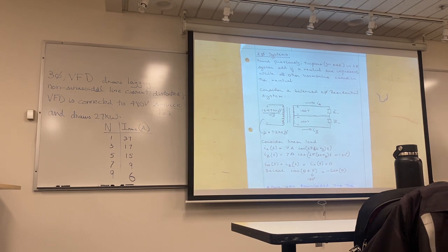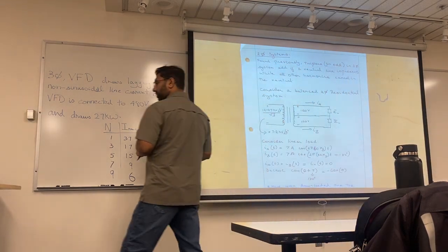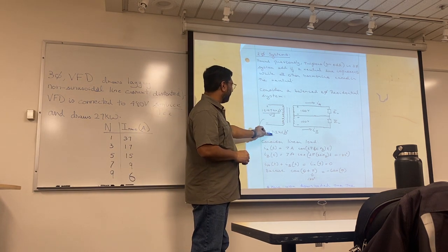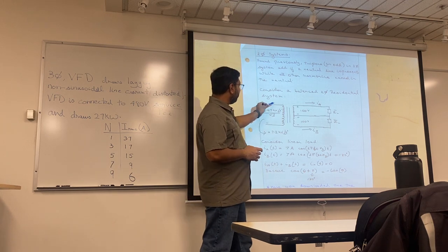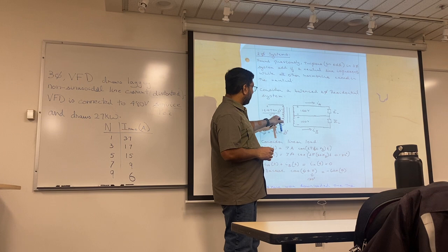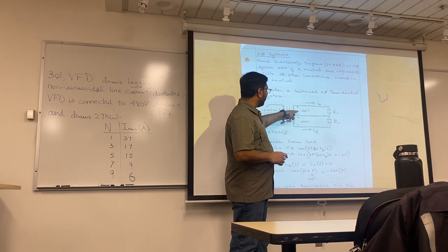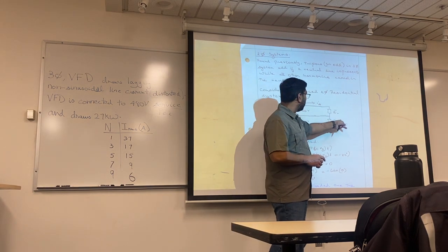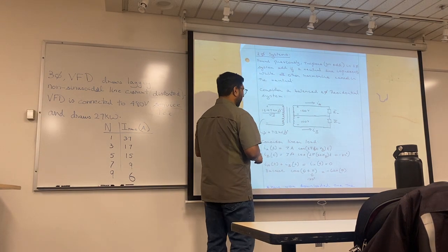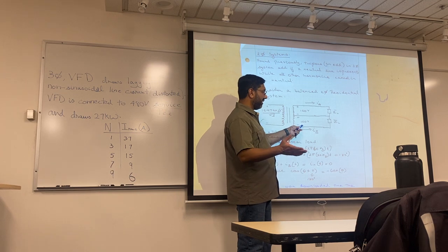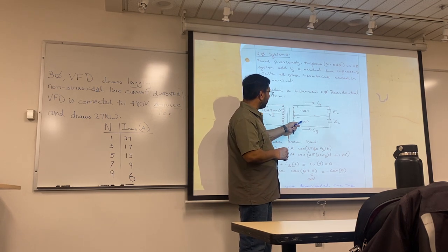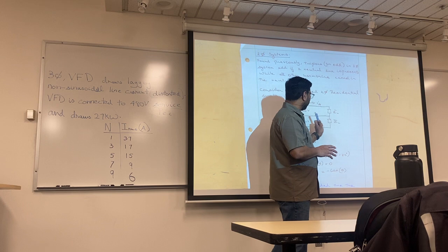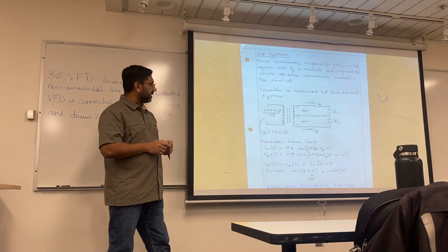Now, someone figured out, and I don't know who that is, that you have 12.47 kV between the lines, and if it's just one line, 7.2 kV, doesn't matter. We do a transformation through some windings. They tapped off the middle of the winding, and that's how you're getting 240 at home. So you have 120 here, 120 here, but if I stick a meter across, you will read 240. So 120 for most of your appliances, the other 120 for the other half, like upstairs, downstairs, depending on how you want to think of it. And then 240 if you have a dryer, for most dryers 240, and there are some electric ovens that need 240, is my understanding.